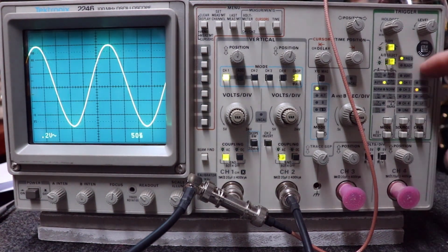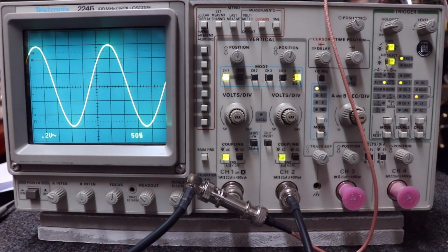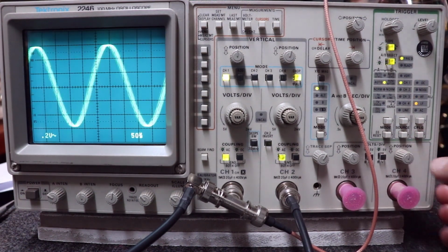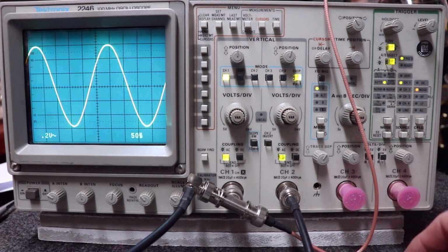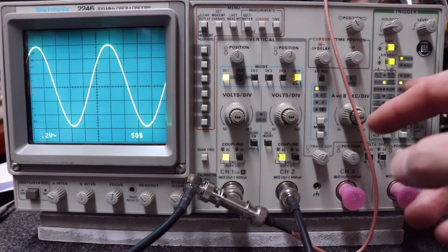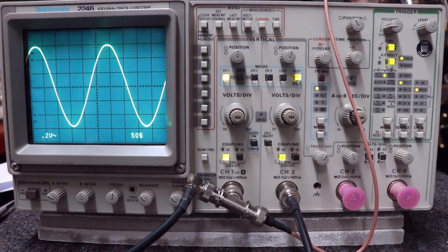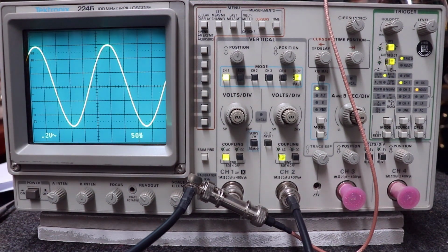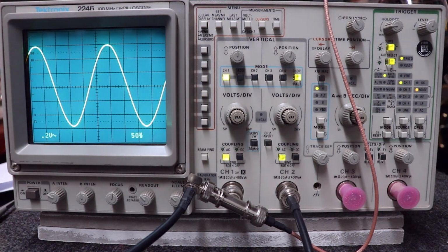This would cut out any noise. This just puts some filters in line. This would cut out some high frequency noise that may be getting in your way, some low frequency noise and whatnot. So at any rate, I typically leave mine on noise over here. I typically leave this triggered on channel 1, and I typically leave this up here triggered totally on auto. The good news is I don't have to touch this 90% of the time when I'm dealing with an audio